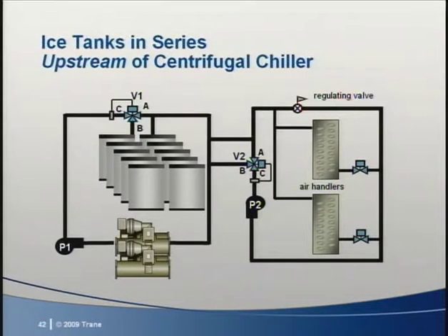Larger systems using centrifugal chillers will see a bigger cost advantage with the ice upstream of the chiller. More storage capacity is available from the tanks if the tank leaving temperature is higher. As the storage hours increase on larger and larger systems, the cost advantage grows because this added capacity starts to avoid the need for several tanks. And centrifugal chillers are quite comfortable making cold water, especially centrifugals that have been optimized for making ice.